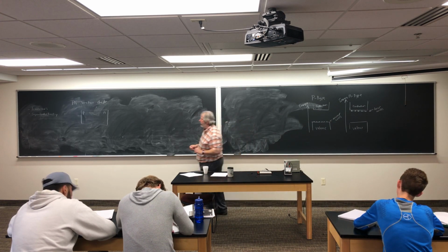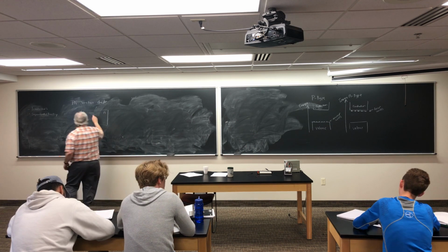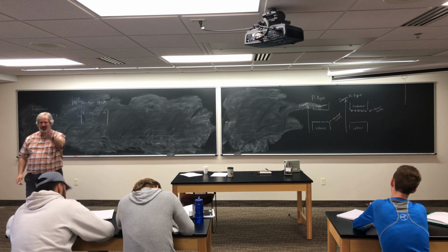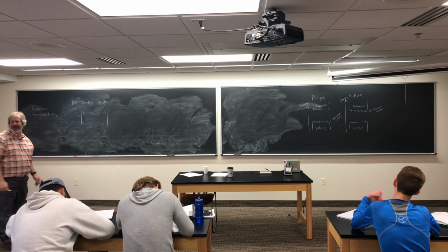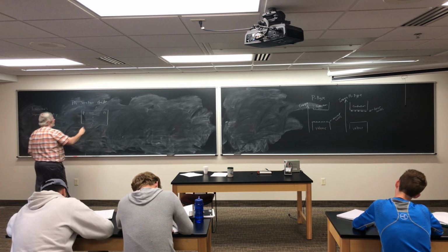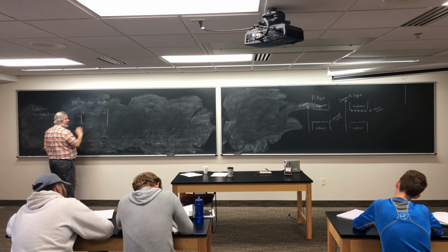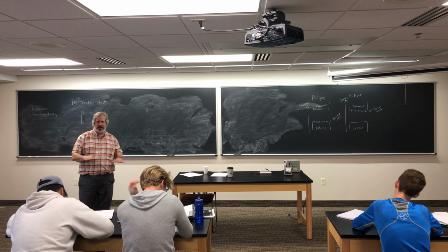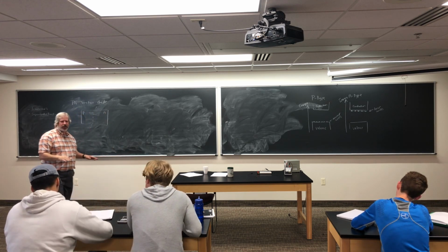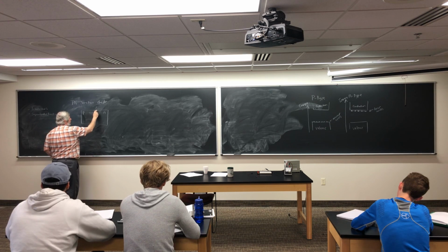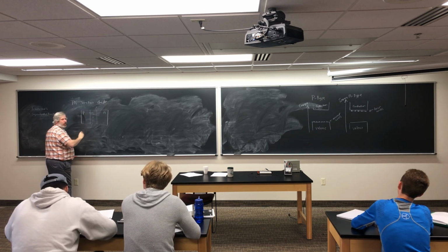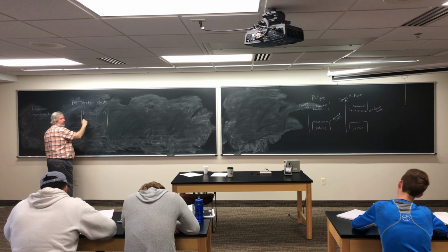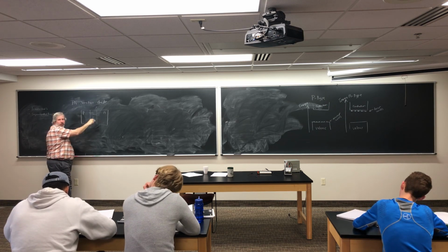For the PN junction, we have this interface, which is never very clean. We always draw a line, but of course it's not that nice, right? And even if we have no bias, if we've not connected any battery to it whatsoever, we still have what we call the depletion zone, right? Where electrons on the N side have moved over and recombined with holes on the other side.